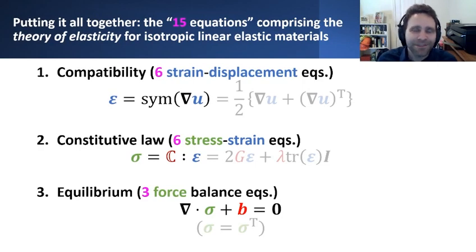And we also supposed that that relationship exhibited isotropic behavior. So the material behavior didn't really exhibit any difference in apparent stretching behavior, regardless of what orientation we decided to stretch this chunk of material in. It would seem to exhibit the same kind of relative stiffness in any kind of direction